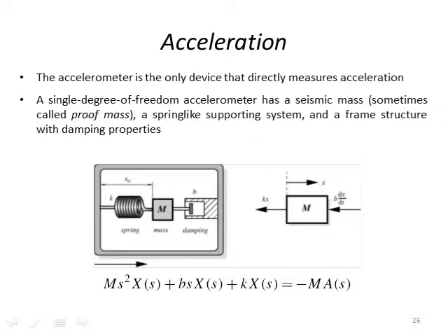Okay. Now you can see the importance of being able to derive transfer functions from these types of operations and being able to analyze those, because for all of these systems, if we want to analyze their behavior and optimize it, we have to be able to make a transfer function for the system and analyze it using either Laplace or Fourier transforms. Typically for this type of system we use a Laplace transform, and then we can take this back into the time domain by doing an inverse Laplace transform.